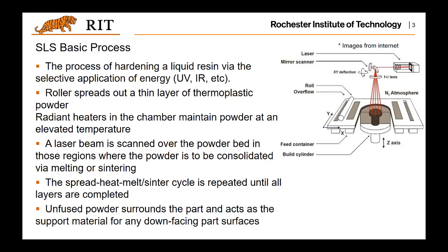And then the leveling roller will spread the material again, and the laser scan happens again to solidify the powder. So the good thing for SLS is it does not need a support material, because the built part is supported by the powder, the excess powder, right?